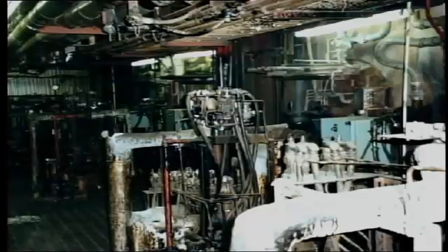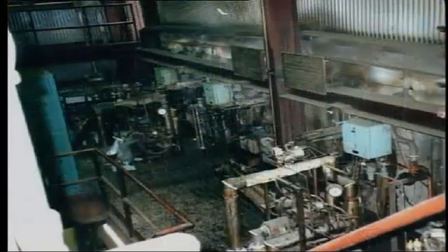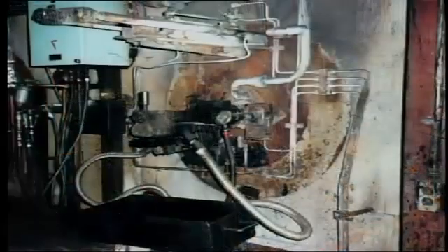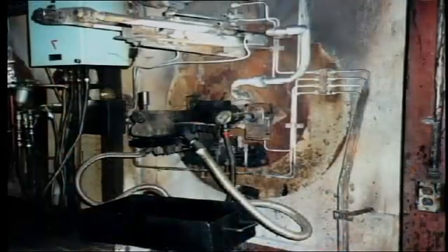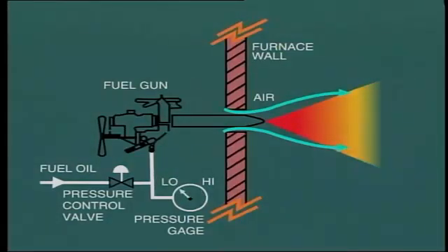Here we see a typical fuel oil burner arrangement. Several burners are provided so as to allow for changes in heat input to the boiler to meet changes in steam demand from the boiler. Individual burners can be taken out of service to reduce load. The quantity of fuel supplied to each burner can also be adjusted.